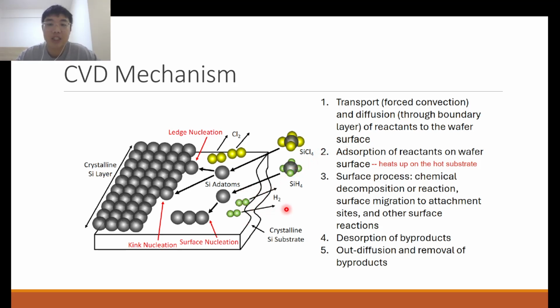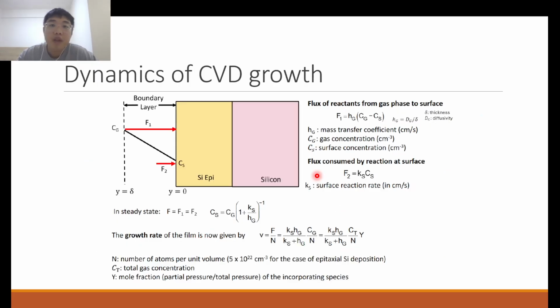Finally, if there are any byproducts, for example, if you're decomposing silane, your byproduct will be hydrogen gas. It will be desorbed from the surface, followed by the diffusion away of these reaction byproducts from the surface. Okay, so what is the dynamics?